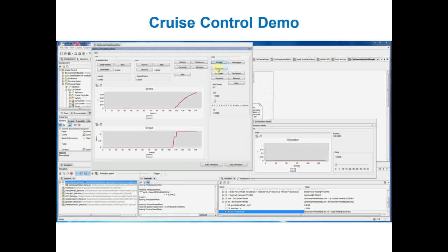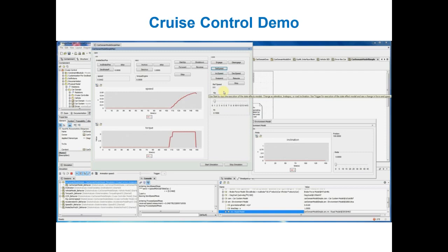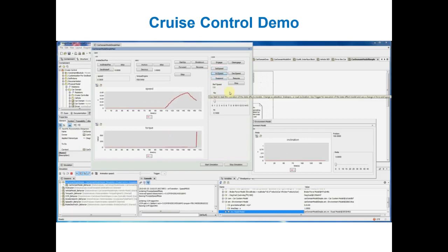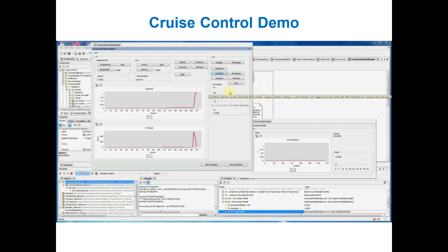the proportional gain. So when you engage the cruise control model and set the speed, here it would not pick up the actual speed, but you have a reference speed, which would be 0. So you would see that the speed goes down, not because it brakes, but because of the friction of the road. It brings it down, and the torque goes to 0 because you are not using the accelerator. As soon as you increase the speed, the torque goes up, and as a consequence, the speed and torque go down and are regulated through the PID controller in order to maintain the speed.